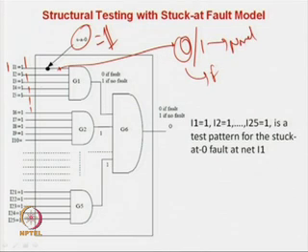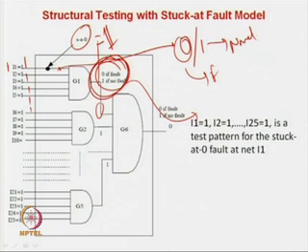But if I somehow apply a 0 over any other inputs, then this effect is not brought out in the picture. Similarly, what you are getting is 0 if the fault is there and 1 if the fault is not there. So again, I have to propagate this effect to the output. As I already told you, I am not putting any pin outs to observe this output, neither am I going to put any multiplexer or any register for that. So now the fault effect is here, that is 0 if the fault is there and 1 if the fault is not, but I am not able to observe it, because I have not got any pin out here. So, no pin out is here.